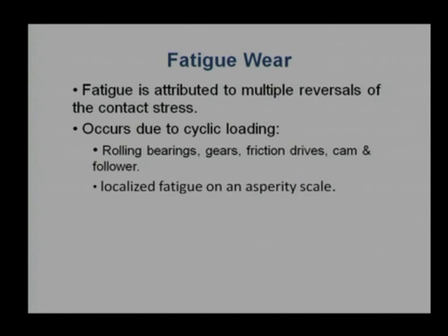Now, we are coming to the new mechanism, what we call the fatigue wear mechanism. Even though I am using the words a new mechanism, I should say that almost all wear mechanisms are one way or another related to fatigue wear. We started with abrasion, then we brought probability into the picture. Probability says that particles are not going to immediately dislodge from the surface. They will go under plastic and elastic deformation, and only after a certain duration will they come to zero. That is when it will be dislodged and removed from the surface. So, fatigue one way or another is related to all mechanisms, it is related to adhesion also.